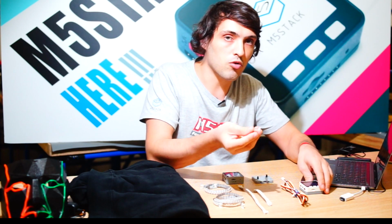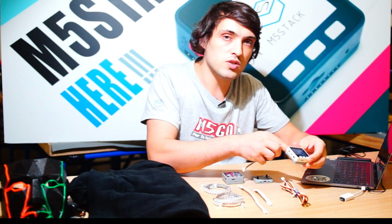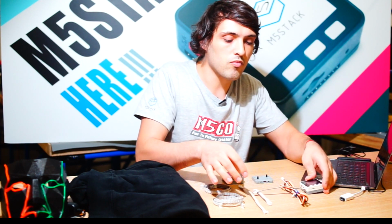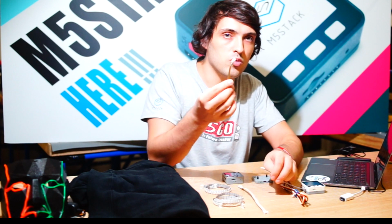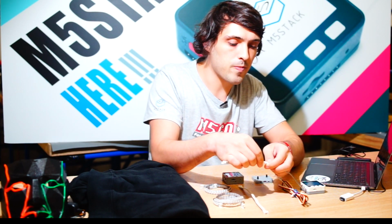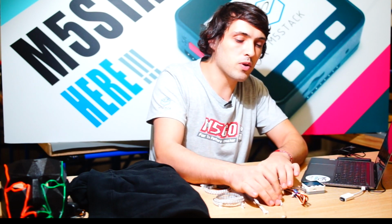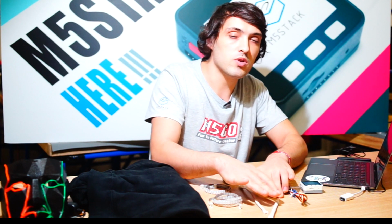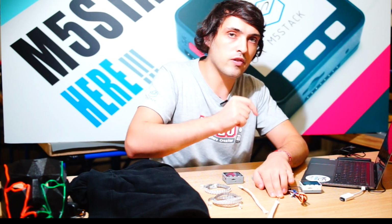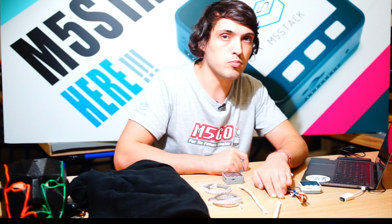First, we'll connect a Grove cable to either port A, B, or C on the M5. And then the other end will connect to the NeoPixel strip. Now we have a strip connected, we can test some simple blinking animations. Let's go to UI Flow and test the simple program.